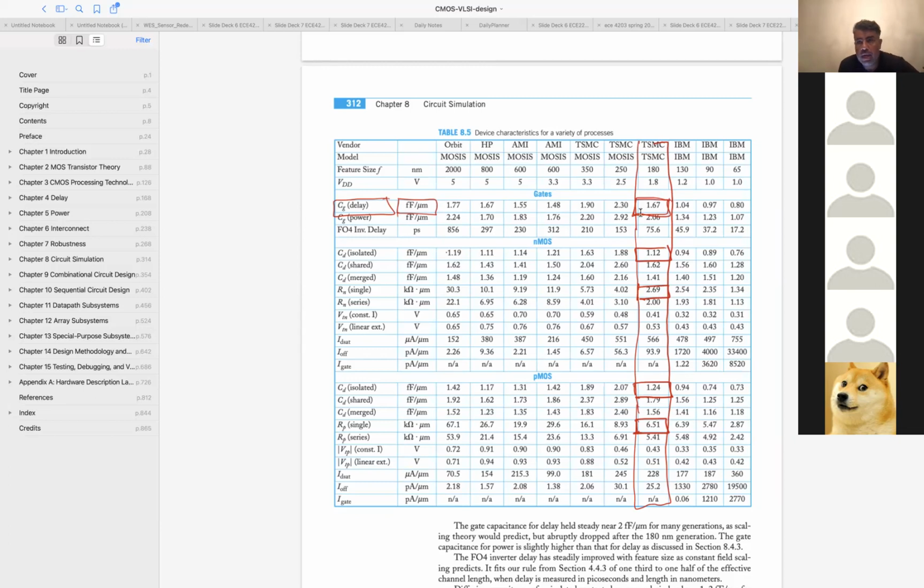We also talked about an effective capacitance. And the capacitance is a little bit easier. So the effective capacitance is just summing up all the capacitances at the output of that device, right? So there is the effective capacitance, say C sub N, at the output of an NMOS.